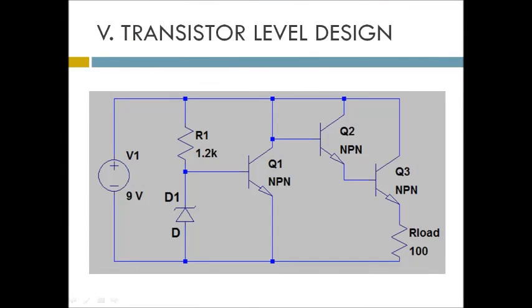With the transistor design of the thermal shutdown circuit, it was composed of a Zener diode, an NPN, and a Darlington pair of transistors. Since the Zener diode has a positive temperature coefficient, as the temperature increases, the voltage at the Zener increases, thereby forcing the current of the base to switch the transistor to the saturation point until the load will be cut off.